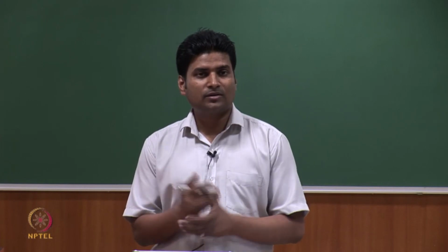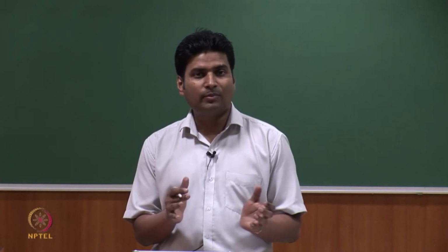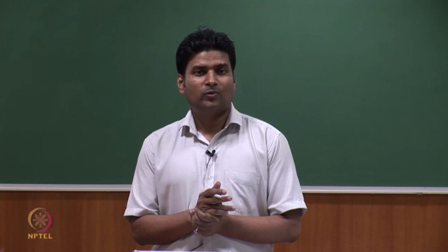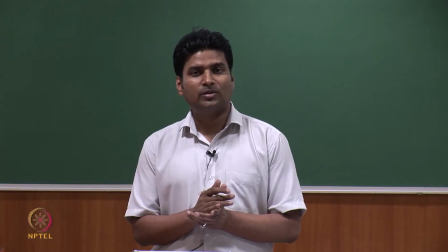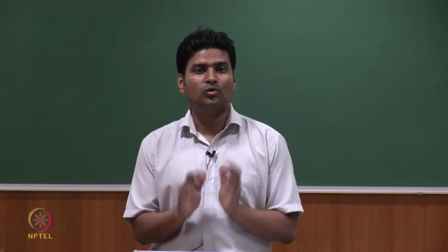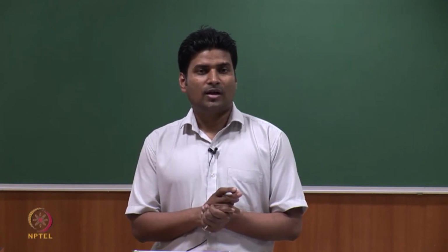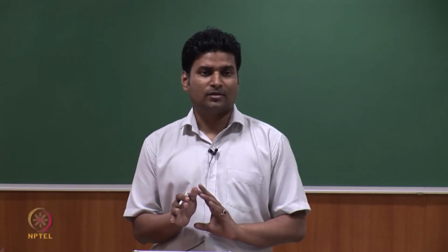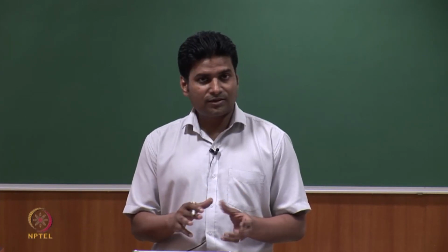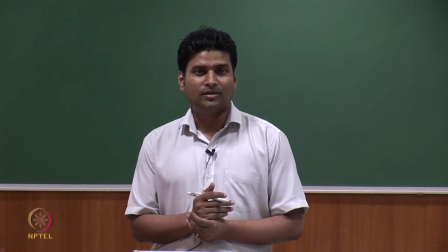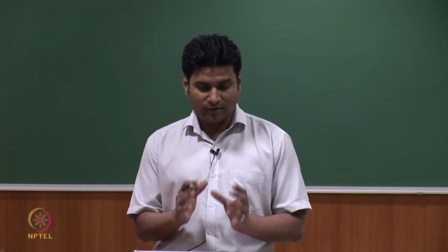So, you simply get sigma and tau on any arbitrary plane with angle alpha, just that the plane has to be such that the normal is perpendicular to E3, otherwise alpha could be anything. So, this is a mathematical formula, is not it. So, you just have to remember this formula,